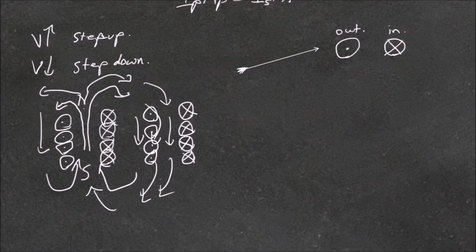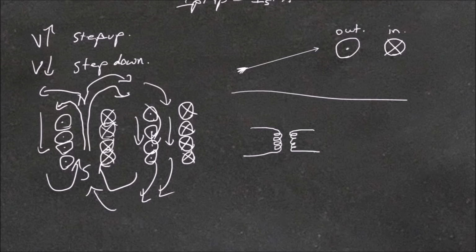So what the iron core does is it provides a good path for this magnetic flux, so it's not just going through the air. So when you're drawing a circuit with a transformer, the symbol is generally a winding, so you get a primary, secondary winding, and usually if it's an iron core, you'd put two lines through there to indicate the iron core. And you can simply draw a transformer as two coils overlapping. You can also put the polarity on the drawing, which will indicate which way the current's going to be coming out of the secondary.